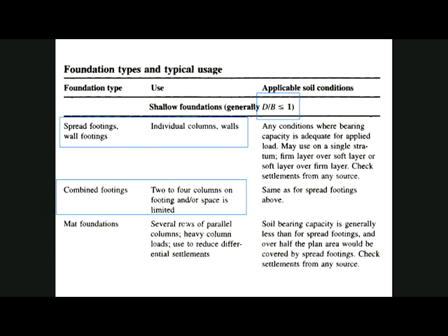So instead of suggesting a deep foundation, we usually try mat foundations when the area is big but the load is small. So that is what we do, mat foundations.